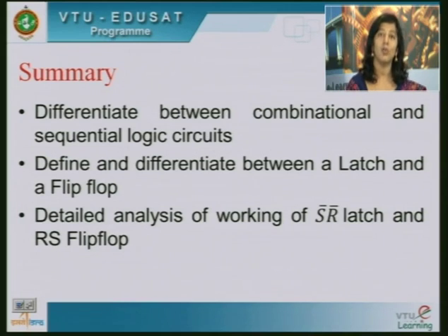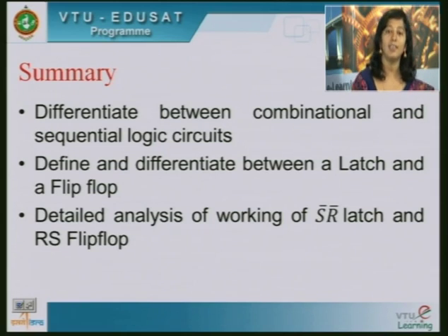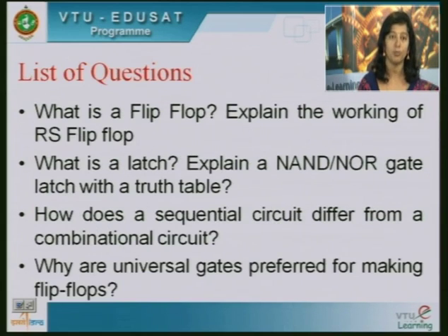We learnt the difference between a latch and a flip flop. A latch works with either no clock and enable or just a level sensitive enable signal, whereas a flip flop works with an edge sensitive clock, either positive or negative edged. Then we analyzed in detail an S bar R bar NAND latch, a NOR latch, as well as an RS flip flop, clocked and gated flip flop.